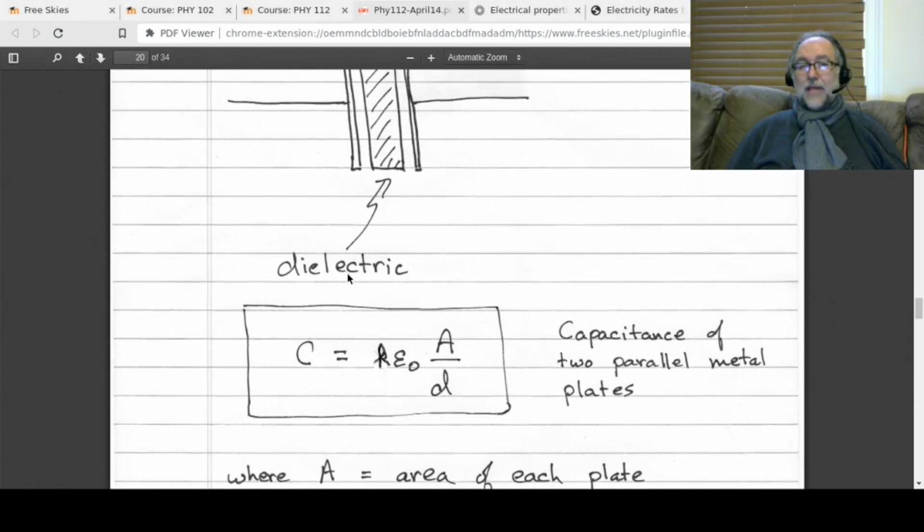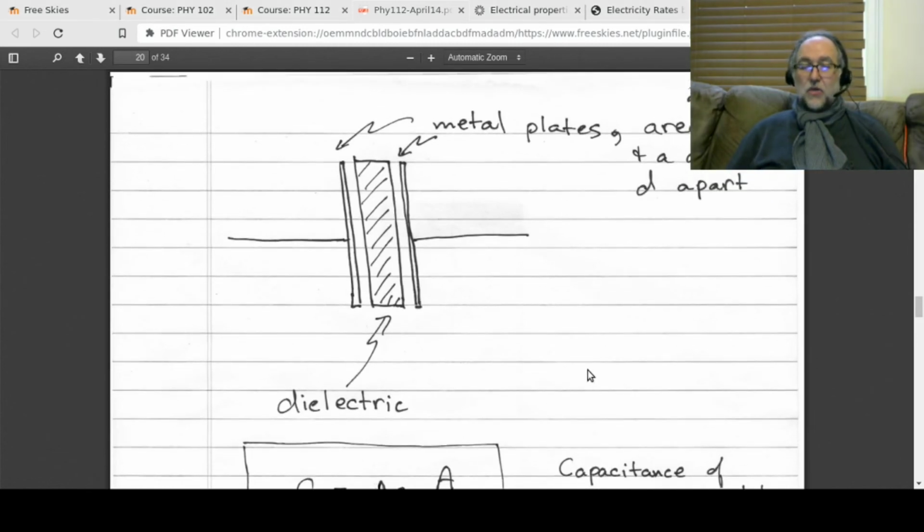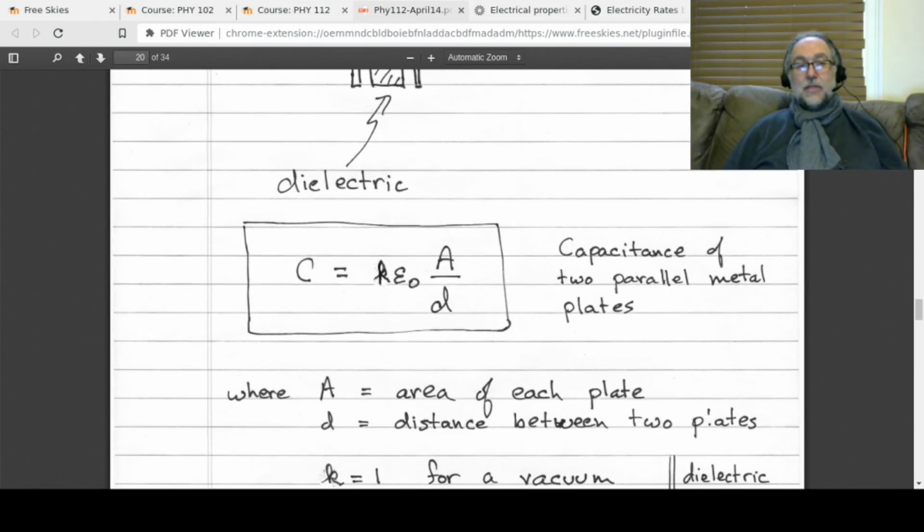All right, remember what a capacitor does. A capacitor basically accumulates charge. The bigger the plates are, the more area there is to accumulate charge. Remember, the negatives don't like being near one another. So if you create a big area on this plate here, say that's the negative plate, you're giving more space to those electrons to spread out, and they're happier being there. And so the bigger the area, the bigger the capacitance, and you can see that in the formula because A is on top. You double A, you're going to double the capacitance.